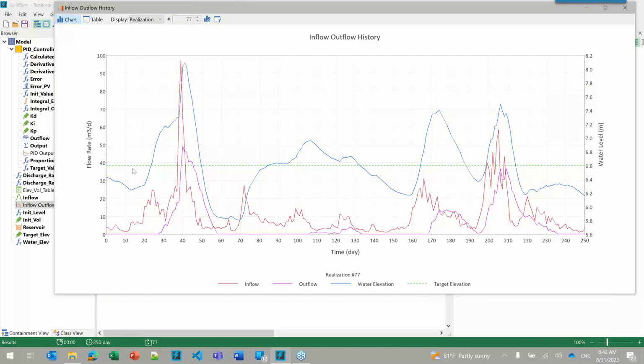So you can see here, it's going below and above, going up and down. And the question is, well, why does it drop down more than before and actually rise above more? And this is because the integral term is being applied more heavily in order to, over the long term, get it to kind of be more equal above and below over a long period of time.